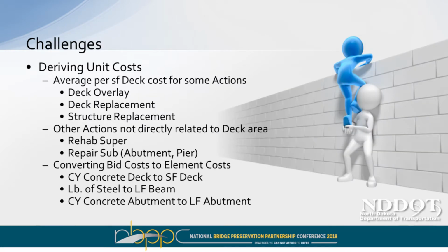Deriving the unit costs, challenging, right? One of the big things is how do you convert bid costs to unit costs for all of these elements, if you're looking at it that way. You're bidding in cubic yards of concrete, you're replacing square foot of deck, and some of those things are really challenging. And again, we have to work on that.